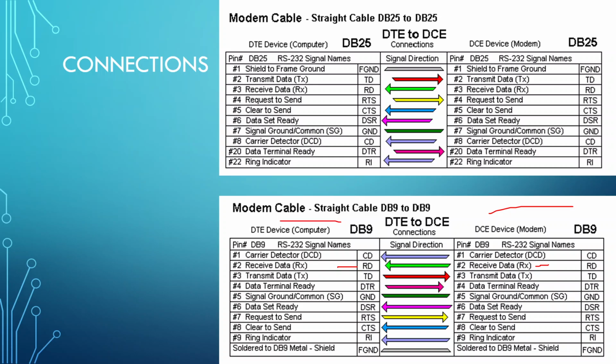So it's really one of those things you have to be careful about when you're setting stuff up, especially if you're manually making connectors or something like that. Just be aware of, did I cross something? Did I not cross something? But anyway, then you can see our DTR, and again, these are all just straight throughs. But it tells you which one's sending information in which direction.